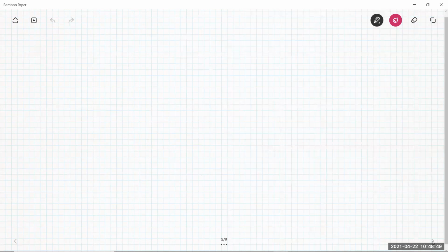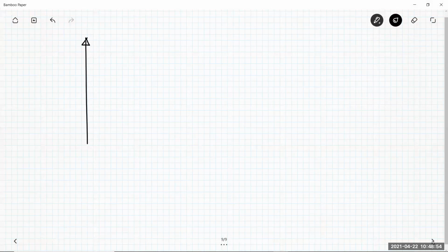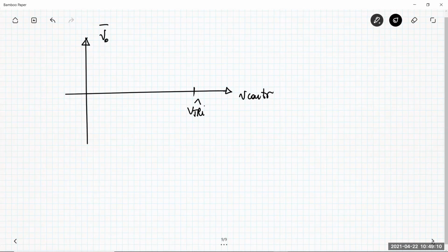Okay, so you also have the possibility to plot this gain expression in a graph, with V control here and V naught average value. We are considering the situation of so-called linear pulse width modulation, in which the control voltage cannot be larger than the peak value of the triangular voltage or lower than 0. Okay, this is what has been discussed so far.